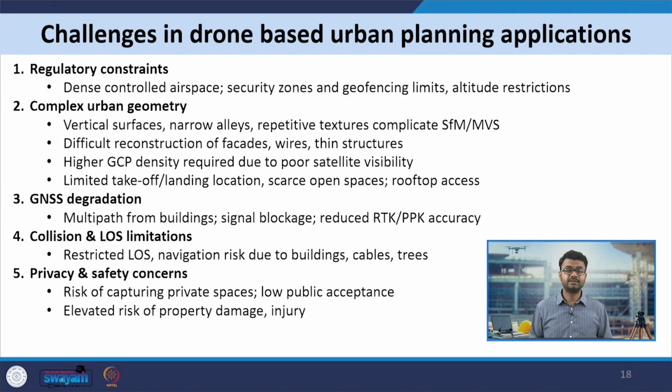So in summary, we can say that outdated surveys and low resolution data lead to poor or uninformed urban planning, which can be overcome tremendously with the use of drones. Drones are useful in urban planning because they enable precise, timely, and three dimensional insight into complex urban environments at various scales, from building structures to a neighborhood scale. And with the high level of detail, they are useful in creating digital urban twins, estimating solar energy potential, environmental planning, damage assessment, and pedestrian and traffic tracking. Thus, as cities expand and planning challenges intensify, drone derived intelligence will become more and more integral to building smarter, safer, and more resilient urban futures.